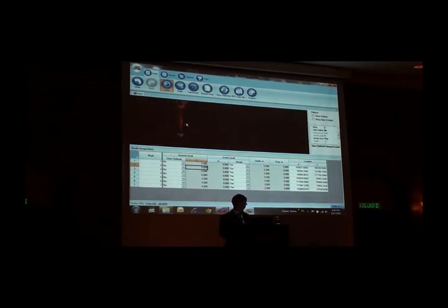We also can edit. Let's say for this last point, node number 5, I change user define to yes, so I can fix a value like 1.2 for the ground level. Okay? If I say no, the program will update. If I move the node, the program will follow the ground level value of the graphical.